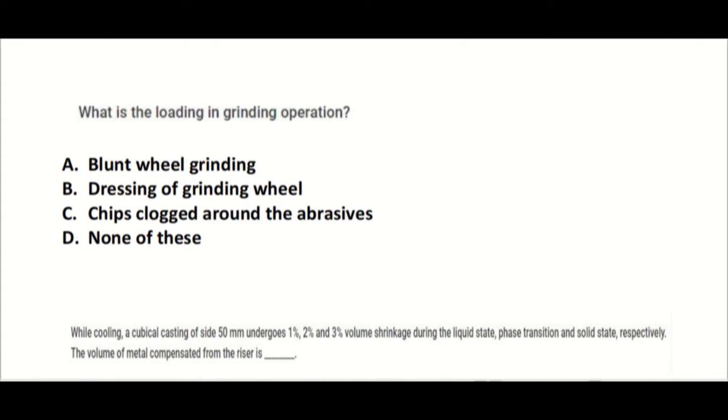We know that the space between the consecutive grains is called structure. When ductile material is ground with a closed structure grinding wheel, long chips will be produced.